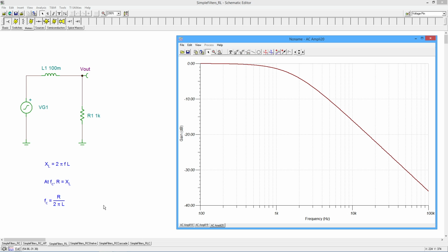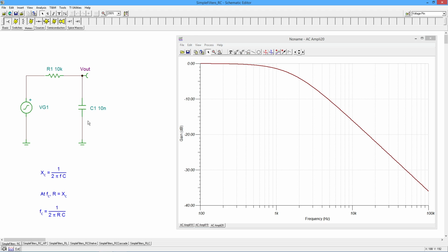Okay, so let's look at a variation. Remind you back where we were with our original resistor and capacitor. So let me throw a resistor in here next to the cap. Now this does something kind of interesting. In the original circuit without the resistance, remember, as high frequencies continue up, this X sub C gets smaller and smaller and smaller, and what we saw out here was the signal at the output getting smaller and smaller and smaller, right? Simple voltage divider.